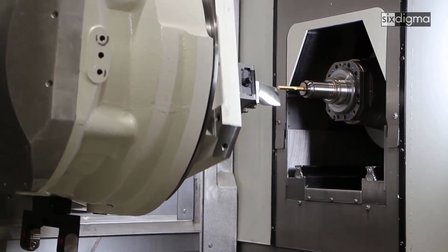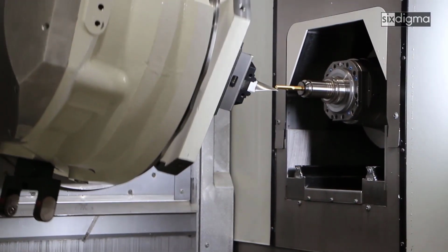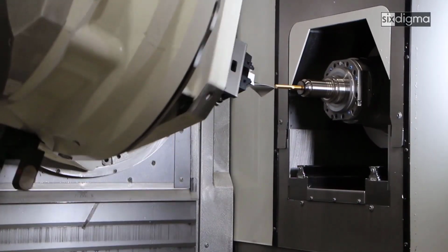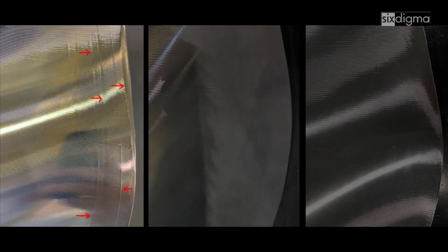The result is a smooth surface that requires no further manual polishing. The tolerance of the part is maintained well under 1/1000th of an inch. Here's a comparison before and after. The image on the left shows surface imperfections caused by axis reversals. The image in the middle shows what it looks like after hours of manual benching. The image on the right shows what we were able to get after the axis correction.